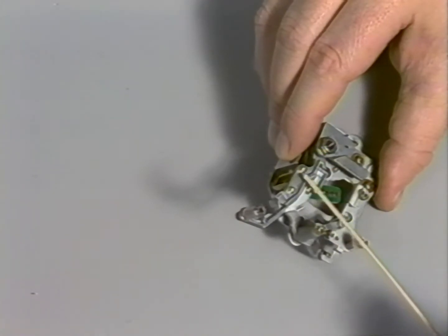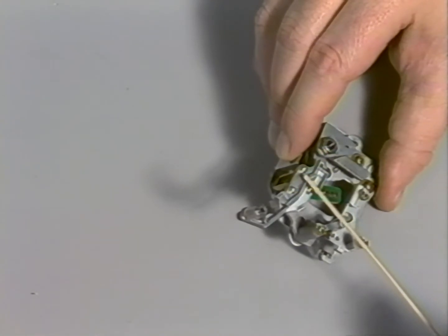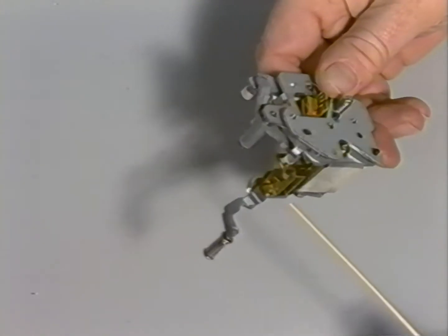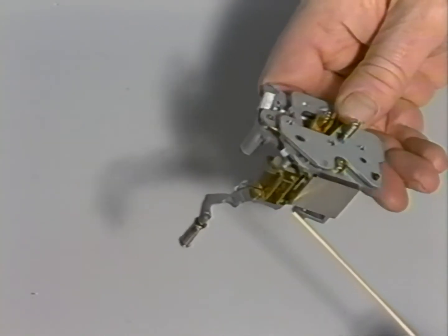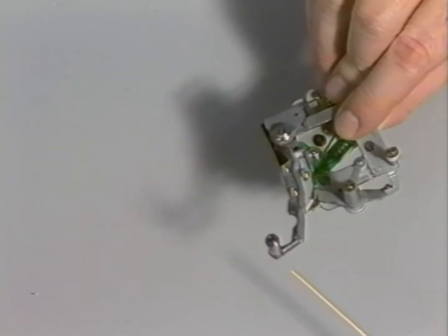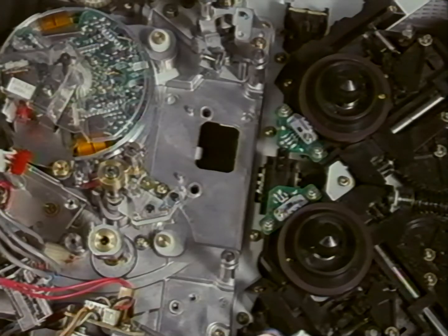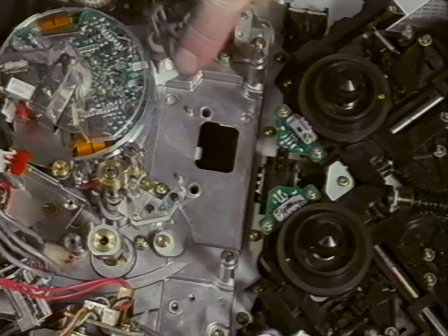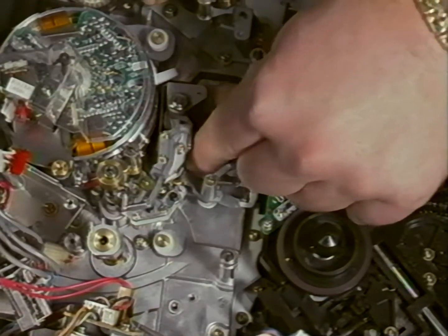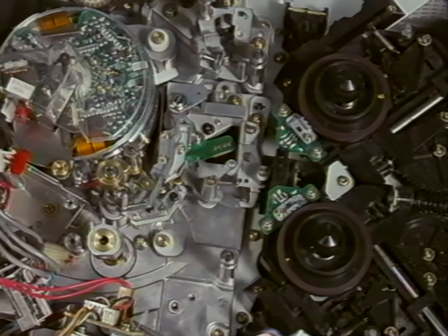Note that the two small screws are held by locking compound. The locking compound needs to be loosened with heat before removing the screws to prevent the screws from being stripped. Now the tension arm assembly is shown being installed. After replacement, the adjustment procedures in Section 523 under replacement of the tension regulator block would have to be performed.